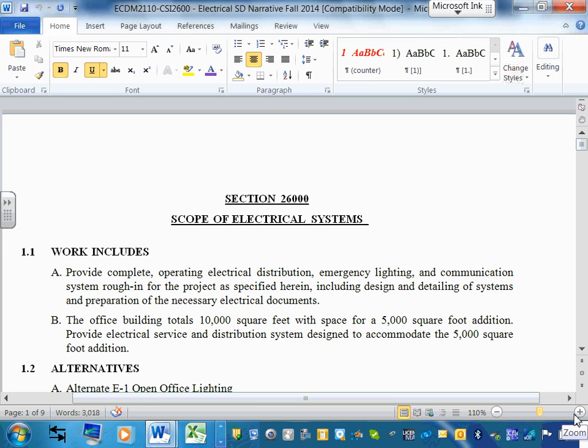Scope. When you do a commercial building, unlike residential, the NEC code book, guys, doesn't say a whole lot about a commercial project. If I ask you right now, what does the National Electrical Code, how many receptacles does the NEC code book require in a room like this? There is no place in the NEC code book that tells you how many receptacles you need in a room like this. If I ask you, how many receptacles do you need in a kitchen in a dwelling, residential? Oh, no problem. In the kitchen, on the countertop, it's 2 by 4, every 2 feet from every opening and 4 in between. Very clear.